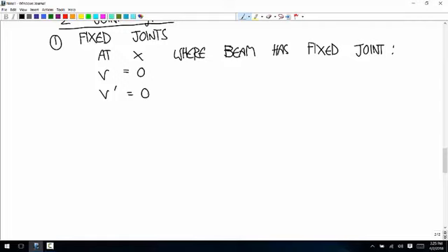Okay, so let me draw that. Let's say that we have a cantilever beam, and that initially the beam has this shape. Then under deformation, the location of this beam and its slope have to stay that way. Then after that, it can do whatever. Yeah, that's very exaggerated, and we wouldn't be able to assume that V prime is equal to 0 there. But right at the wall, we have V equals 0, and V prime is equal to 0.